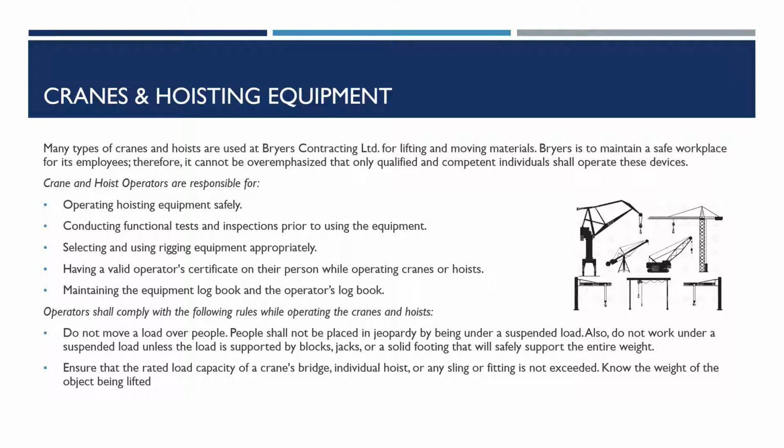Ensure that the rated load capacity of the crane's bridge, individual hoist, or any sling or fitting is not exceeded. Note the weight of the object being lifted.